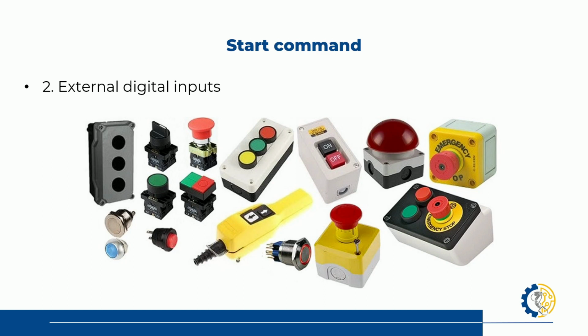So at the moment when they activate this button, they add, as far as I can remember, 2 normally closed contacts. They press it, they obviously open up, and that's what causes the drive to stop. That is very dangerous. It's not right, and also we're stopping and starting our drive in a forced manner, diminishing the useful lifetime of the appliance.